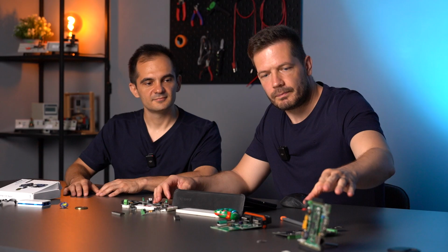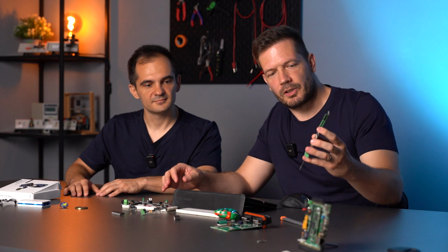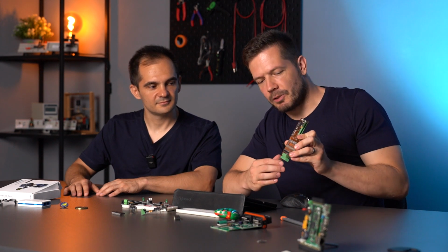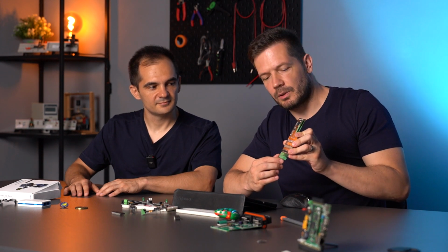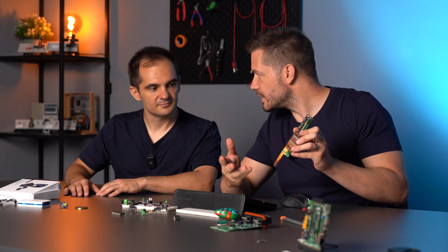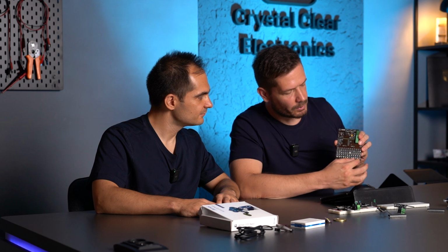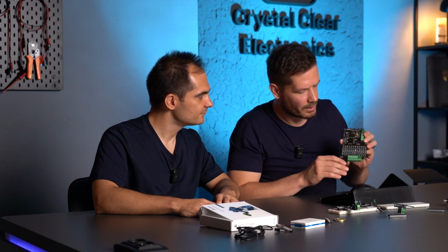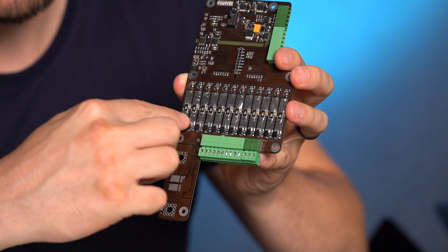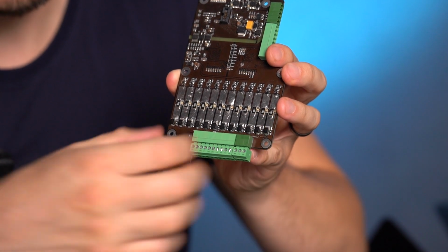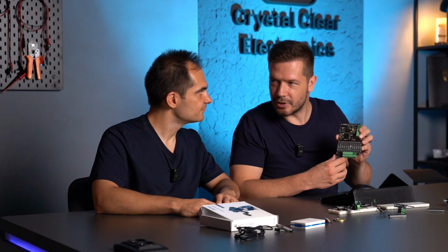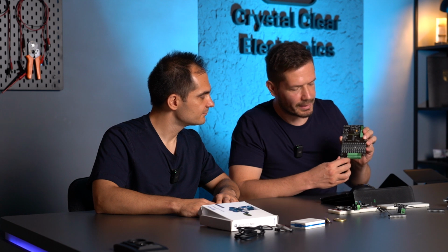Now that we've seen how many places microcontrollers are used, let's look at a specific example from the automotive industry. We've brought with us these 3 PCBs, which is an electronics for battery management. So it does the management of the batteries. It's easy to recognize this because there's this part where you have the same circuit with diodes, transistors, repeating 12 times. The point is that I can see that there are 12 iterations. This indicates that there are 12 cells of battery management being done by this electronics.